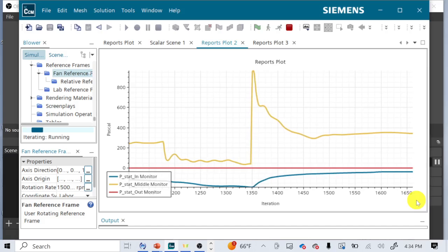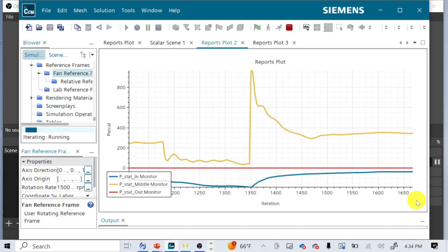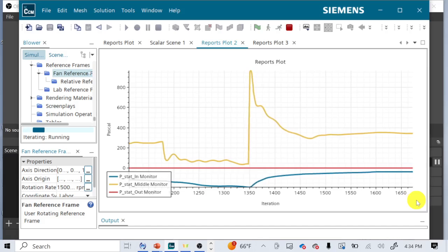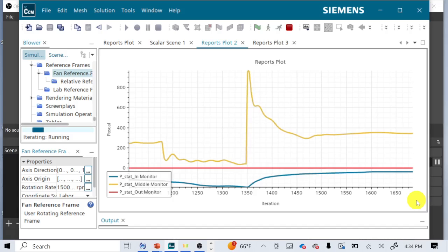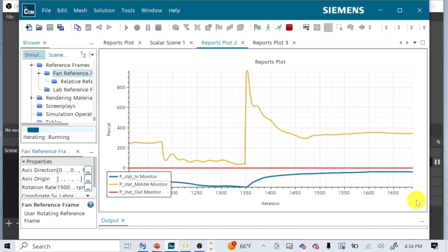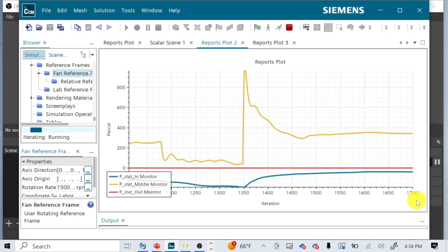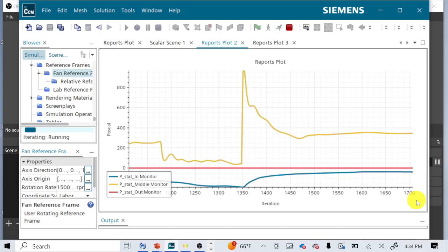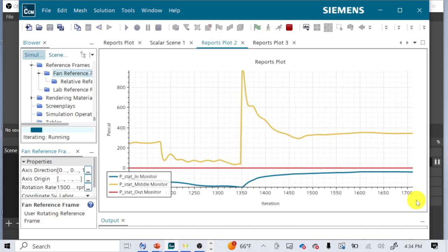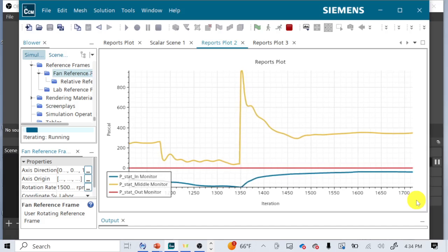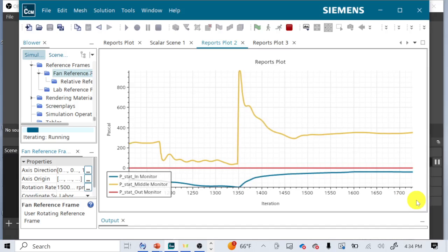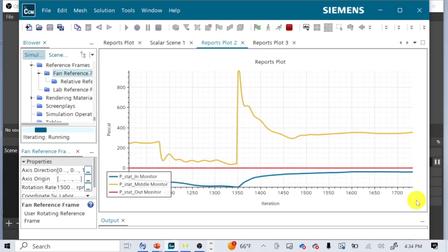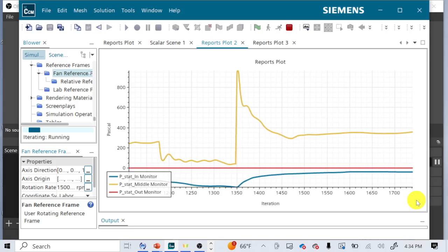This is changing the static pressure by top to bottom. It's probably 450 pascals. A standard atmosphere is 100,000, so it's changing it by about 0.5% currently. It might change it by a couple whole percentage points at 3,000 RPM, especially if the resistance is high. So think about what other quantities might potentially change. They're not going to be probably as interesting as these ones, but think about some other quantities, because I guarantee there's a couple of them that are worthy of at least looking at to see how much they change.